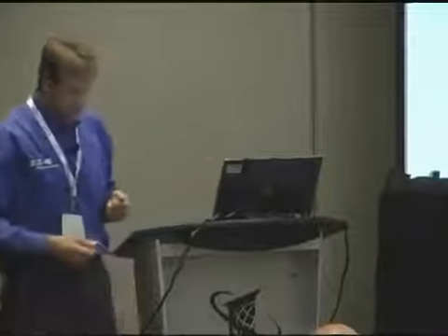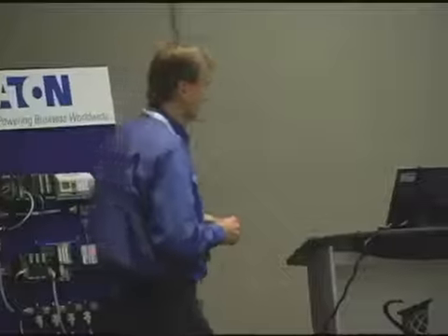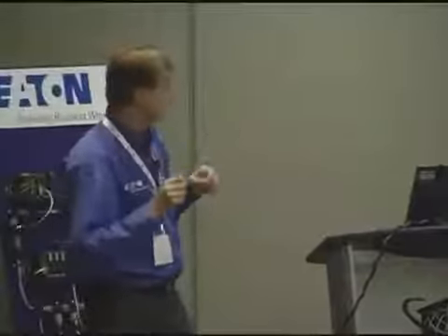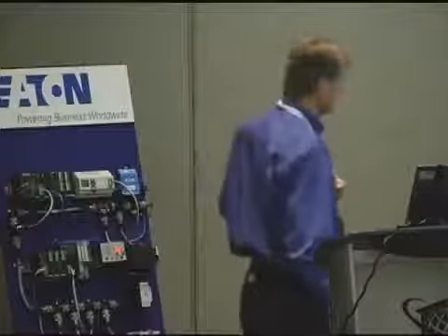Termination. A cable has a characteristic impedance. And if we want to eliminate that reflection thing, we have to terminate at both ends. So we put impedance matching terminators on. A serial cable can be anywhere from 100 ohms to 150 ohms, but given the characteristics of that particular cable, we would put terminators on both ends to get away from reflections.